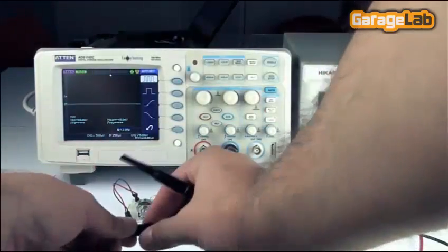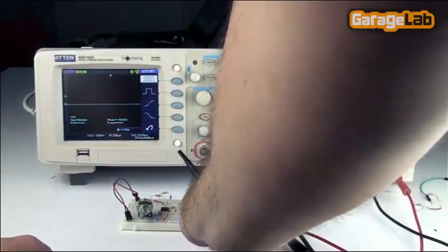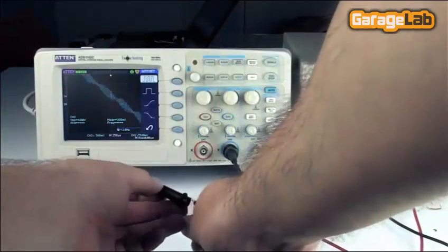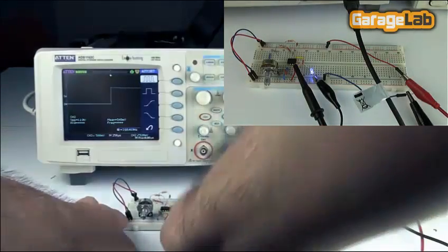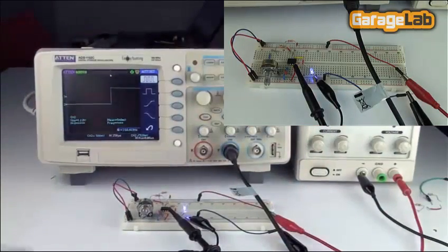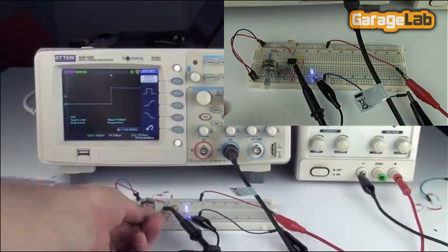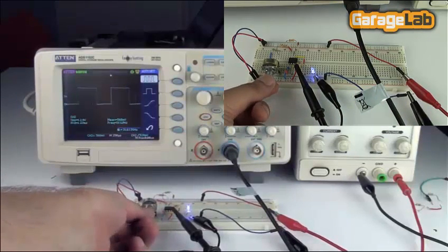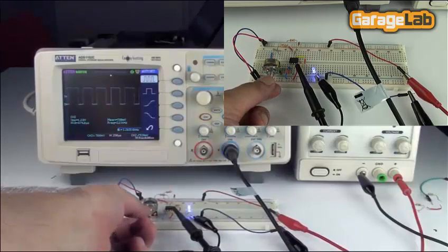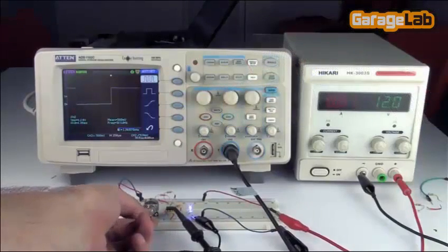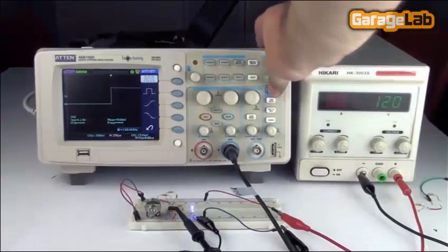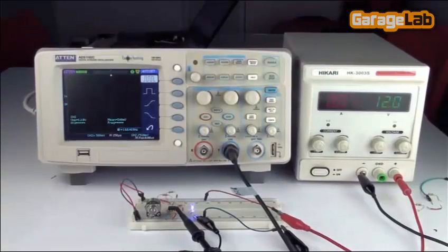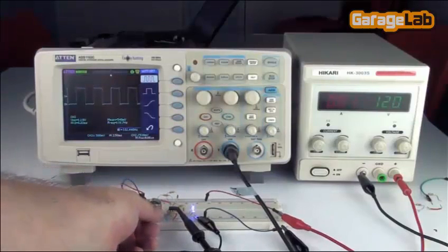Now we connect the oscilloscope cable to the resistor leg connected at the pin 3 and the other tip of the cable to the ground, as shown in the image above. As you can see, a square wave was generated on the screen. Notice that by varying the potentiometer, we vary the wave frequency. This circuit is varying the frequency in a range nearly from 140 Hz to 1.9 kHz.